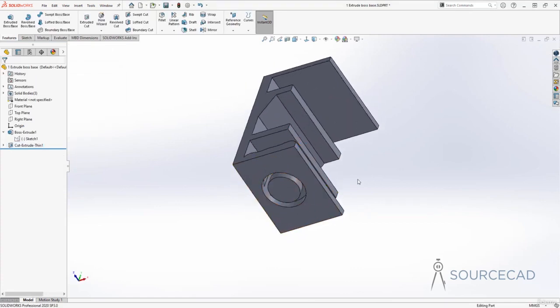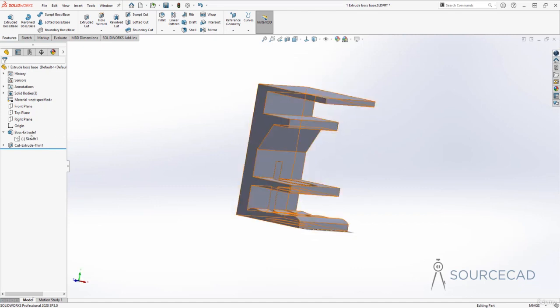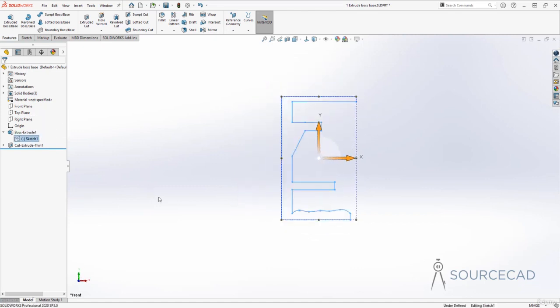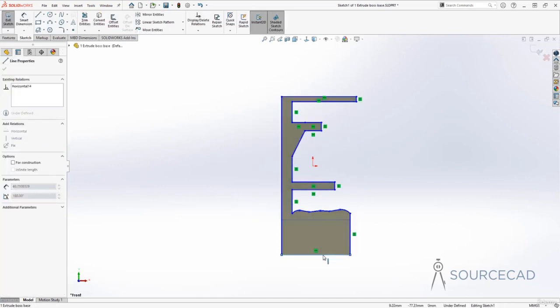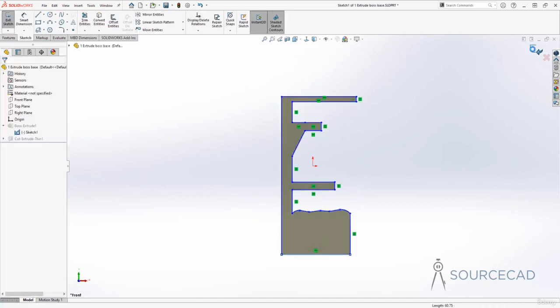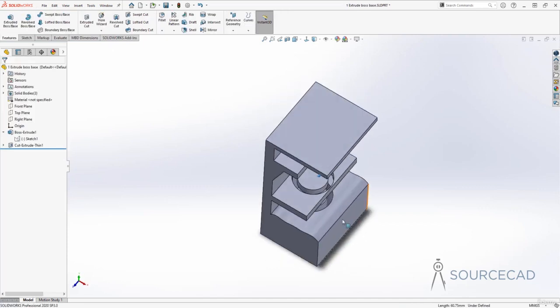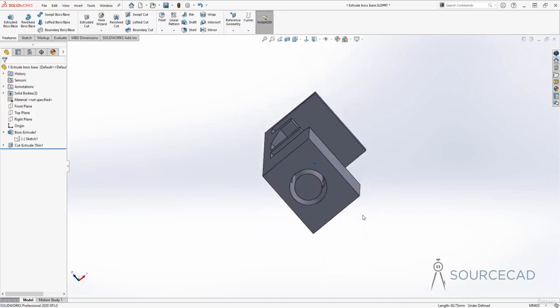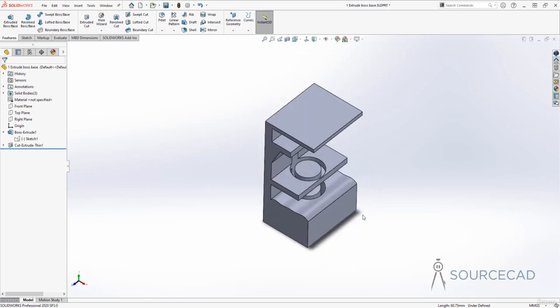So apparently there is no difference, but when you now go to the main sketch, which is this one, and modify this, even if you increase the height, no matter how much you increase that, it will respect that design intent and make a completely clean cut all the way through, because that's what we specified using the through all option. That's the reason why you should always keep design intent in mind whenever designing anything in SolidWorks, so that even after you make changes, the changes are honored for all the parts and features that you add later on. And that's all about the extruded cut feature.